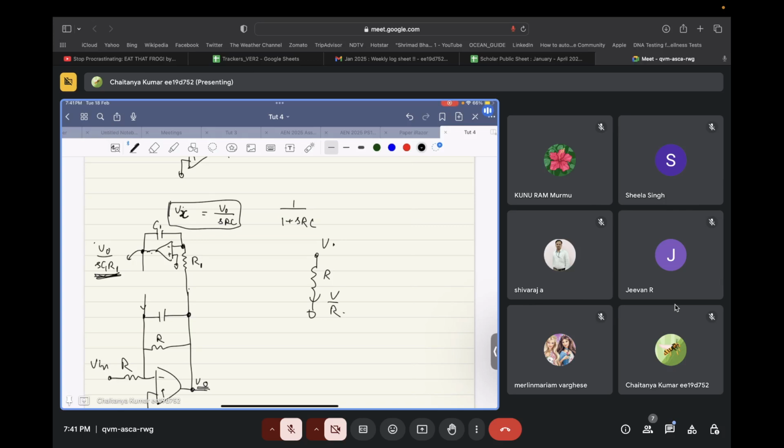So for this RC integrator, the sign will be negative over here, right? It's -1 by C1R1, correct? So what happens is, now if you directly connect a resistor between the two, let's call this R2, what will happen? The current will be inversely proportional to frequency. That functionality we achieved, but the current will be flowing in the opposite direction.